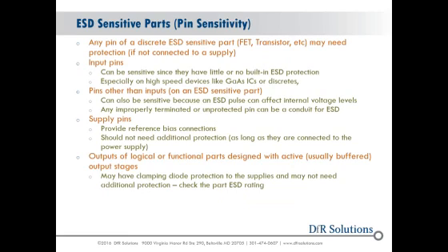Okay. If we look at things from a pin sensitivity perspective, that can be any pin of a discrete ESD-sensitive part. It might be a FET transistor. It might need protection if it's not directly connected to a power supply. Input pins, because they have little or no built-in ESD protection, are vulnerable, more so on high-speed devices like gallium arsenide.